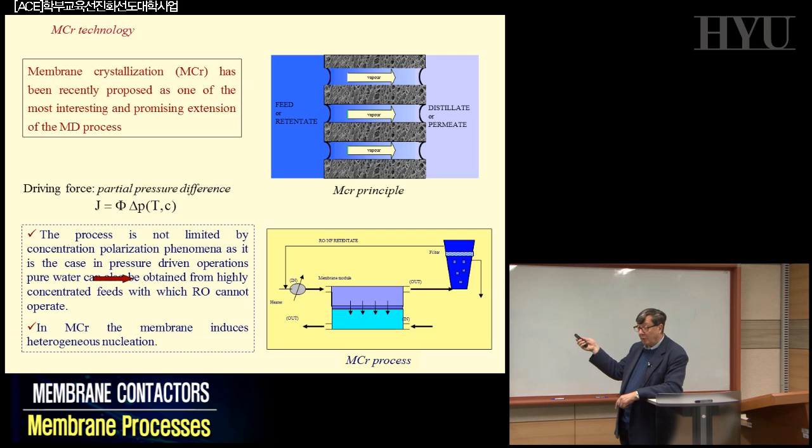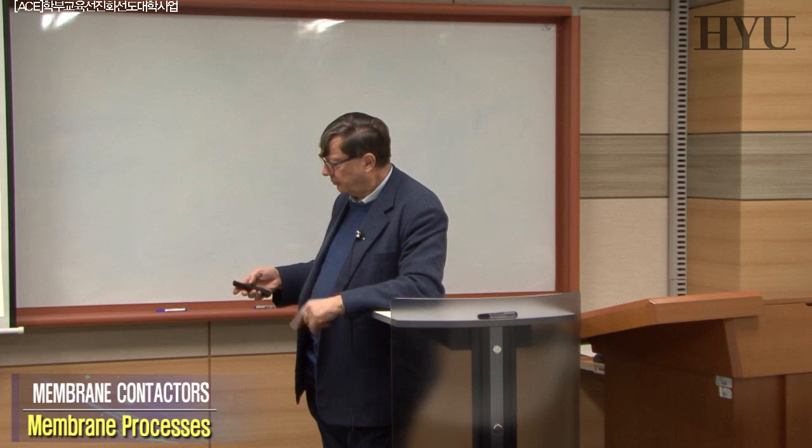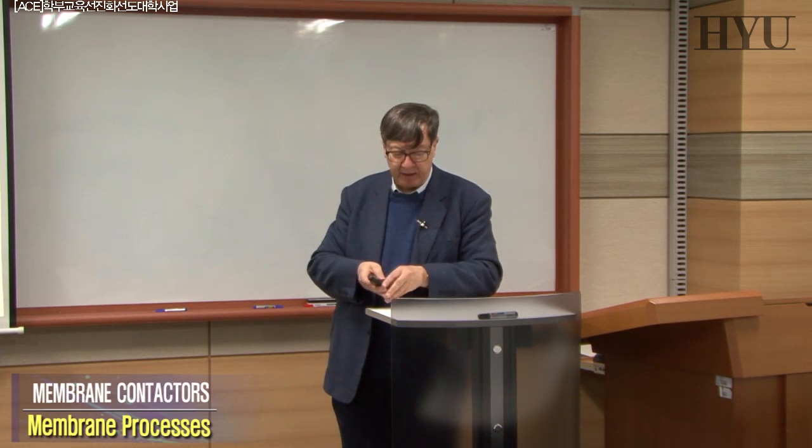Now, when you work in this way, where you can control a lot of parameters in a very interesting way, all the interfaces of concentration, etc., you can produce not magnesium sulfate, you produce epsomite. And for epsomite, people pay you $20, $15 per kilo. So forget about the water, and you just sell epsomite, and that is the real benefit. And that is quite interesting because all these new unit operations are improving the performance of the traditional ones they are competing with. So we will start to discuss membrane crystallizers next time.